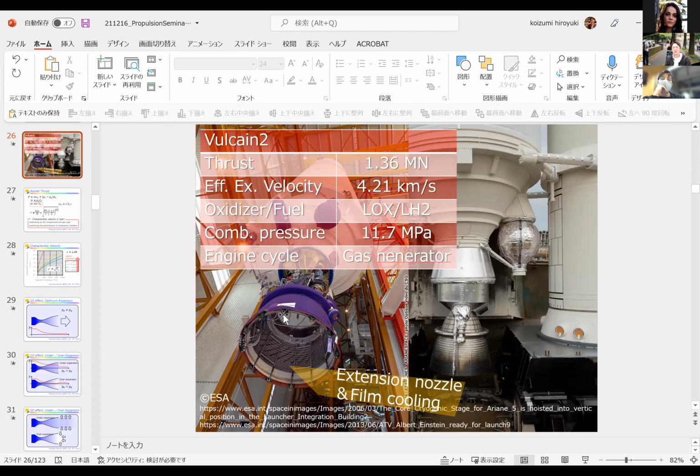Yes, the main problem is cooling, I think. It's an inverted shape, and access to that inverted core is not easy. All of the parts should be cooled properly for a bi-propellant thruster, and it's not easy in the case of an aerospike engine. Ideally, it's very nice. It can get very high performance from the ground to the orbit. Many researchers have studied it, but it's not yet been realized as an actual rocket engine.